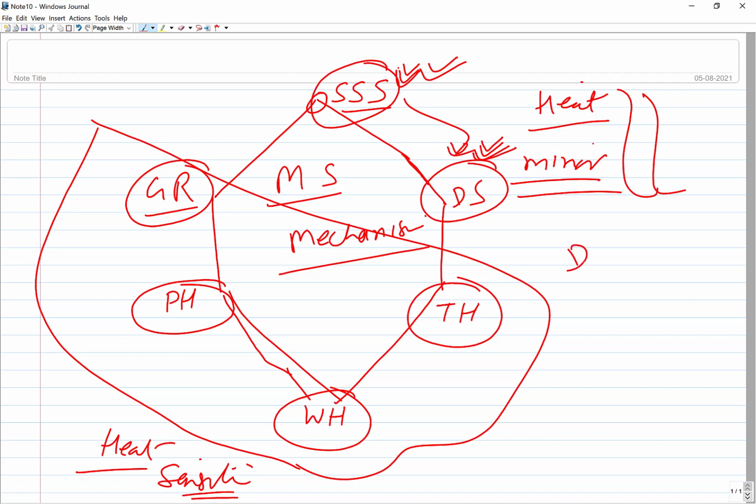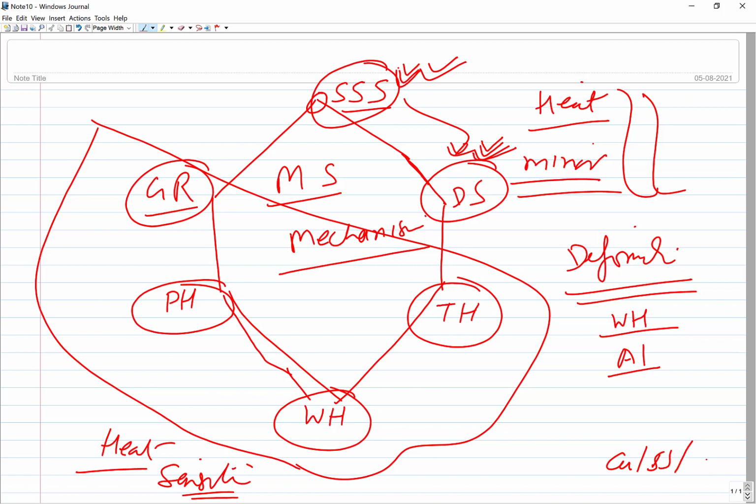The second aspect is deformation. Most of the metals show work hardening behavior due to strain hardening, but there is always a huge relative ranking for that. A few get strengthened very heavily as compared to others. For example, aluminium doesn't get strengthened much due to work hardening as compared to, say, copper or stainless steel or maybe cobalt.